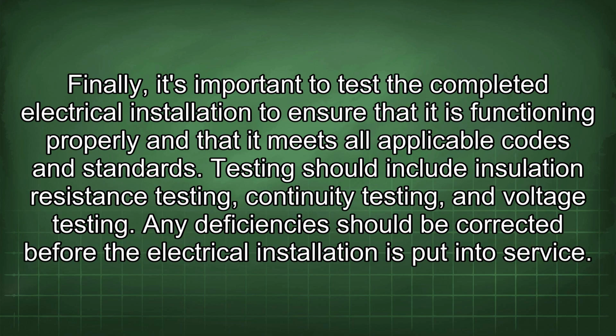Finally, it's important to test the completed electrical installation to ensure that it is functioning properly and that it meets all applicable codes and standards. Testing should include insulation resistance testing, continuity testing, and voltage testing. Any deficiencies should be corrected before the electrical installation is put into service.